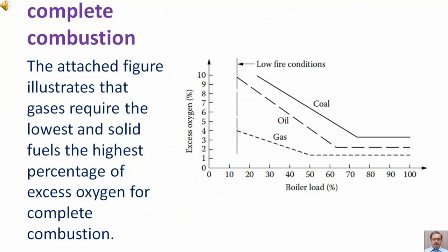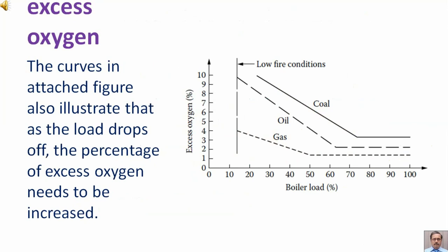The attached figure illustrates that gases require the lowest and solid fuels the highest percentage of excess oxygen for complete combustion. The curves in the attached figure also illustrate that as the load drops off, the percentage of excess oxygen needs to be increased.